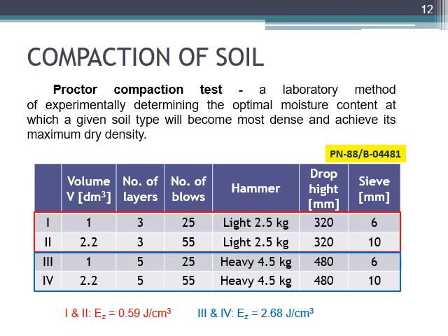The optimum water content and the maximum dry density are very important parameters of soil because they let us know at what water content we shall compact our soil while, for instance, building an embankment. To check these values in a laboratory, we have to use some standard method.